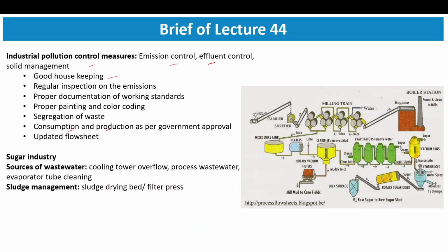Now, the juice which is produced is our concern. This juice has a majority of water and is very dilute. So the next step is to remove certain solids and impurities by adding lime and some sulfur dioxide, and later we pass it through evaporators to get concentrated juice.